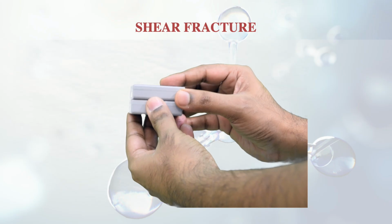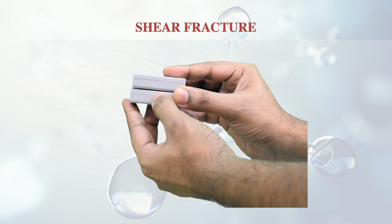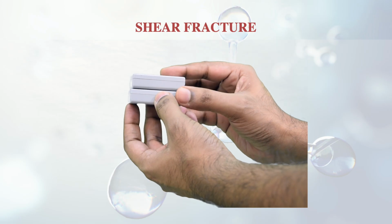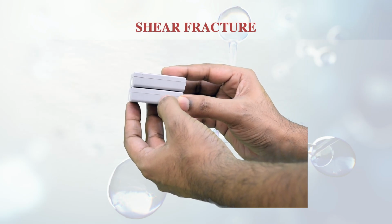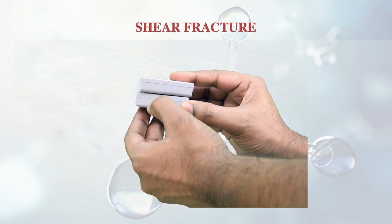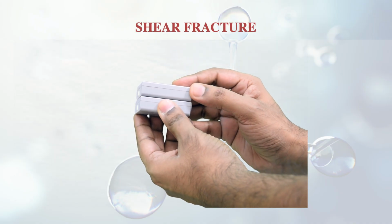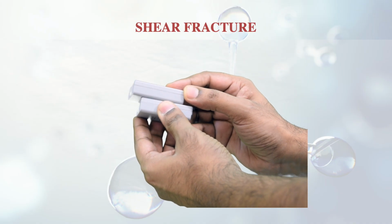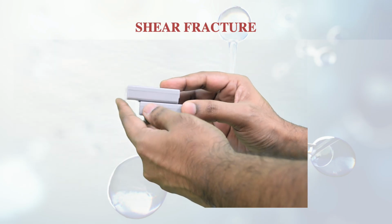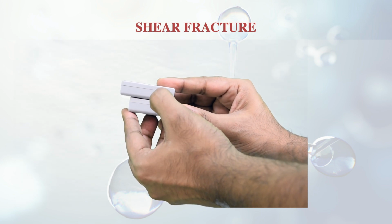Suppose this is the specimen, and these are certain layers of the particular specimen, as you can see in the figure. Different layers are there, and if shear is taking place, slipping takes place, and only the middle planes of this specimen slip. Suppose this is one small plane up to this level and the other one is up to this level. If only these two are slipping, then the crack will be slanting type, because the upper portion is not moving completely. Whereas if the whole body slips, then this will be completely perpendicular, vertical type. So the crack will not be slanting in that case.